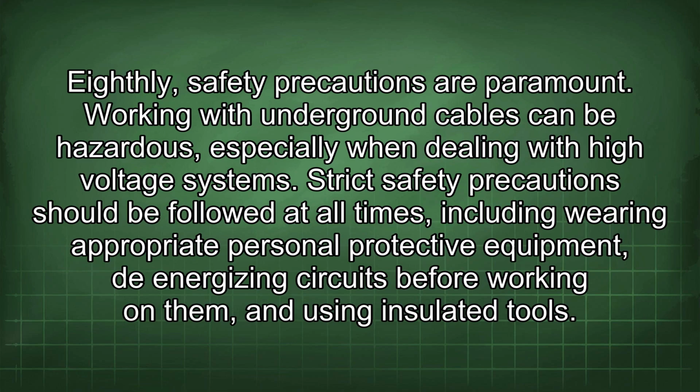Working with underground cables can be hazardous, especially when dealing with high voltage systems. Strict safety precautions should be followed at all times, including wearing appropriate personal protective equipment, de-energizing circuits before working on them, and using insulated tools.